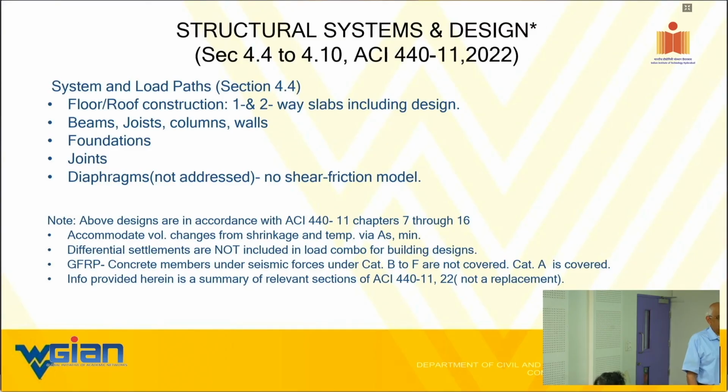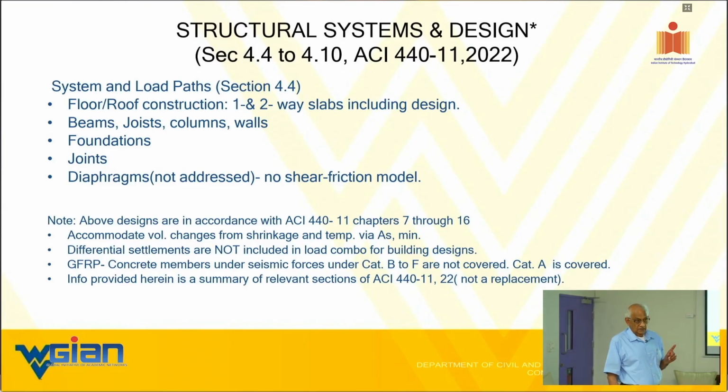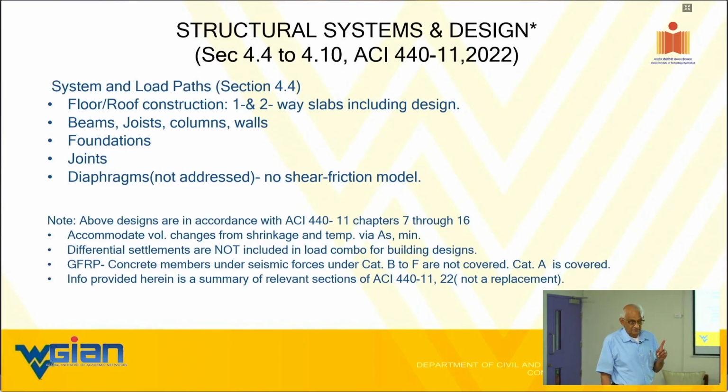Even in an earthquake we are facing the problem. Well, yes, that is true, but we are not talking about that kind of differential settlement. What we are talking about is differential settlement with time. The one you're talking about is a dynamic response. Here it is more like a creep type, a time-dependent response.